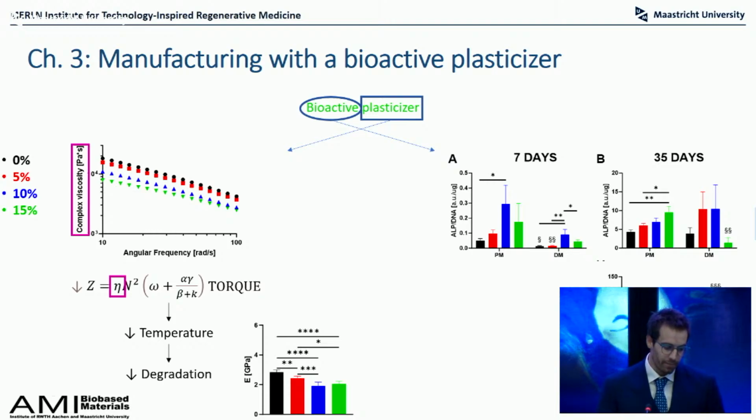So far, to compensate for higher viscosities, tissue engineers would just raise the temperature, which is the main factor driving thermal degradation. By applying this strategy, we can do nothing but decrease the manufacturing temperature and therefore slow down degradation. Interestingly, this came at very little expense of mechanical moduli, as you can see from the graph.